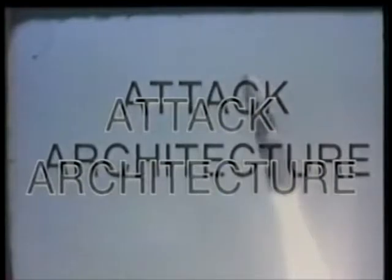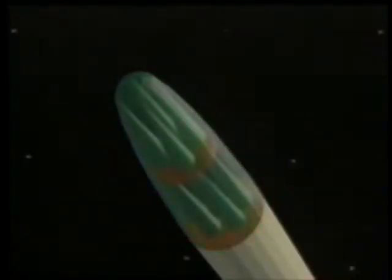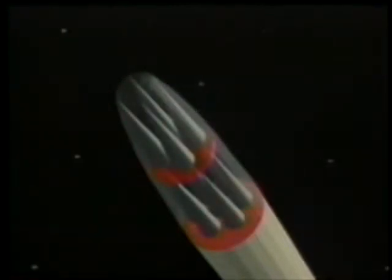To defeat a ballistic missile, you have to understand how it works and how much time you have. The lifespan of a ballistic missile is only 30 minutes. In that time, it gets up and out of the Earth's atmosphere and goes through 3 distinctive phases. In the first phase, which includes both boost and post-boost, the missile is leaving a white-hot plume, and it's carrying all of its warheads in one platform or bus.